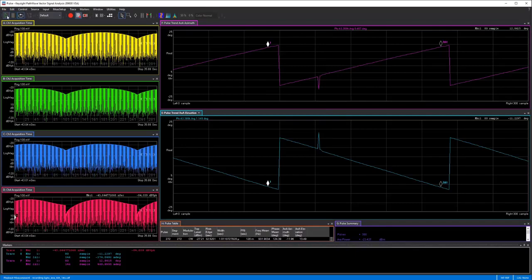And we're going to hit play, just so you can see that it's a live updating measurement. And we see some phase discontinuity here, and that's due to this quick phase discontinuity jump that we have built into our scenario of interest. So I'm going to select pause again, and we're going to use the marker capability to really understand the start and stop angles of this particular measurement.